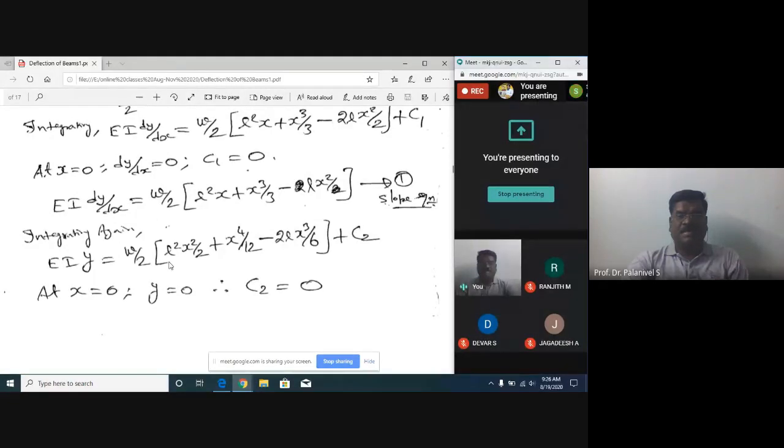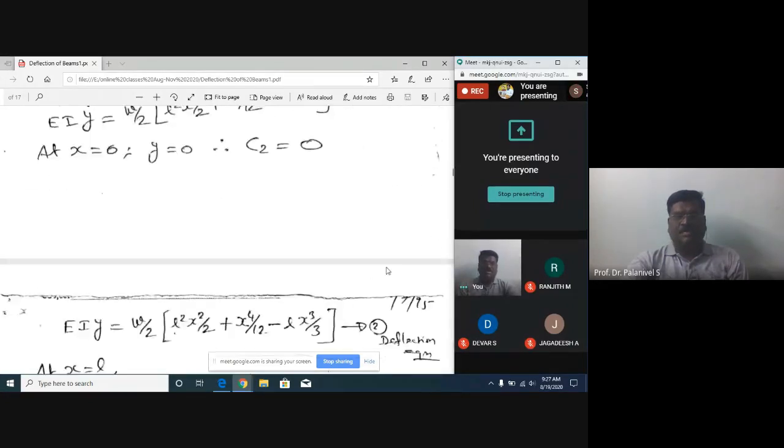At x is equal to 0, now you apply the boundary condition. We know at the fixed end the deflection is 0. If you face any problem, you tell me. In case you are not able to listen to my audio or something, you tell me. At x is equal to 0, the deflection at the fixed end is 0, y equal to 0. Therefore, the integral constant C2 becomes 0.